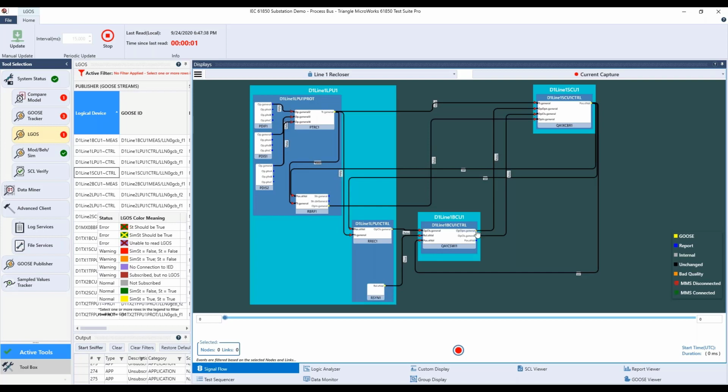And then here, what we already discussed before, we have the op open and op close, which is going into our logical node XCBR. So now this is the static configuration. We also show some internal signals. Those are not from GOOSE messages. They are not necessarily sent as GOOSE messages to this breaker failure. We can still capture them from the GOOSE message to visualize. And then you, of course, have also the internal signals that operate from the different protection elements that go into the trip.